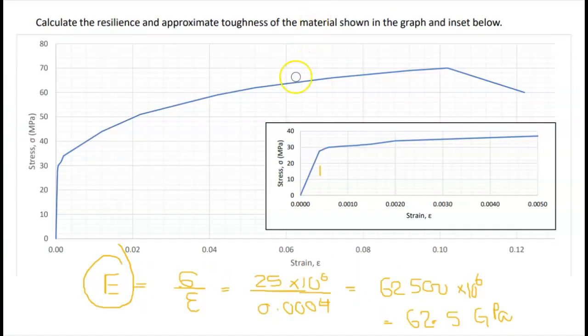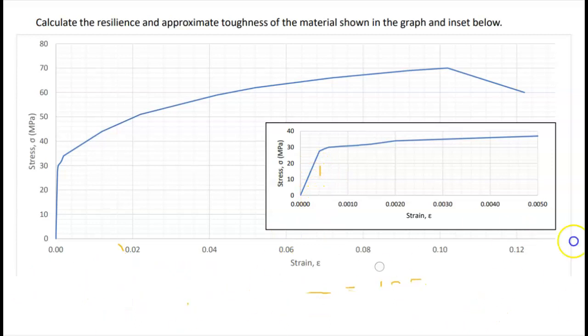Okay, now this one. This is from the tests today, so I've just plotted the graph. Here, this is the normal version, and that's the zoomed version of it. If I want to find the value for the Young's modulus or elastic modulus, I zoom this graph in, and that's what I got. I need to find this value and this value.